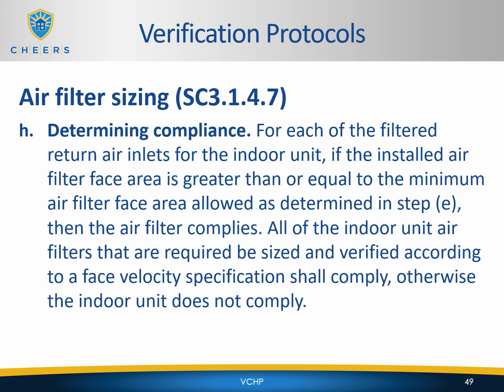Determining compliance. For each of the filtered return air inlets for the indoor unit, if the installed air filter face area is greater than or equal to the minimum air filter face area allowed as determined in step E, then the air filter complies. All of the indoor unit air filters that are required to be sized and verified according to a face velocity specification shall comply, otherwise the indoor unit does not comply.